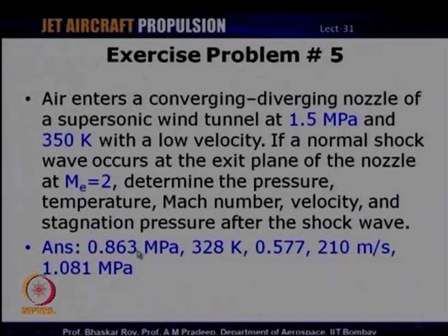The pressure is 0.863 megapascal, temperature would be 328 Kelvin, the Mach number is 0.577, velocity is 210 meters per second and the stagnation pressure is 1.081 megapascal. So, these are a few exercise problems that you can solve.